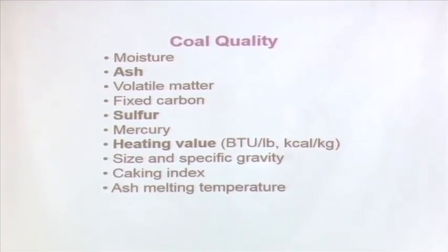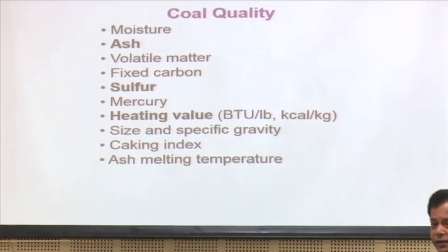So, I add coal, for the supply of C, then you get CO2 plus CO and like that you are basically trying to reduce. And whatever impurities are there with the iron and your coal, they also have to be separated, otherwise the effective volume of your furnace will be reduced. So, they have to be converted into a molten stage. Normally the major impurities are silicates.